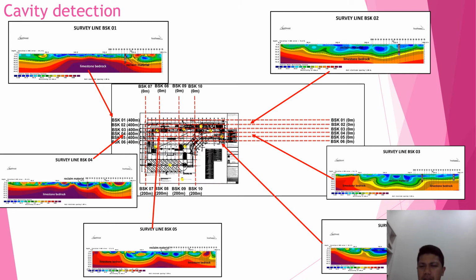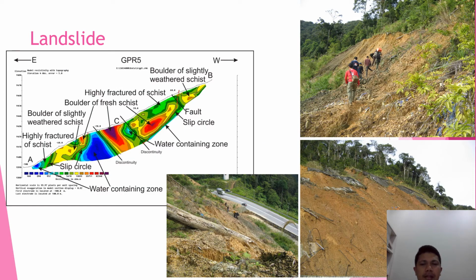But here you can see the profile is undulating, so maybe it is representative of the pinnacle of limestone beneath the surface here. For me it's very clear. Maybe after they remove several meters of topsoil, you can find the pinnacle of limestone. So this is very useful to engineers, to help them get some idea how they can set the piling to the hard layer.